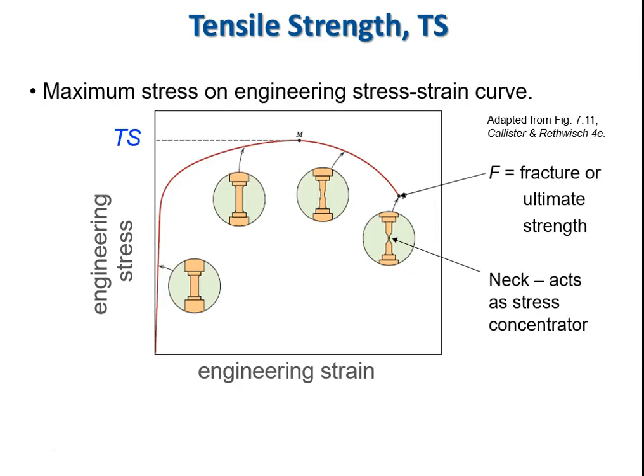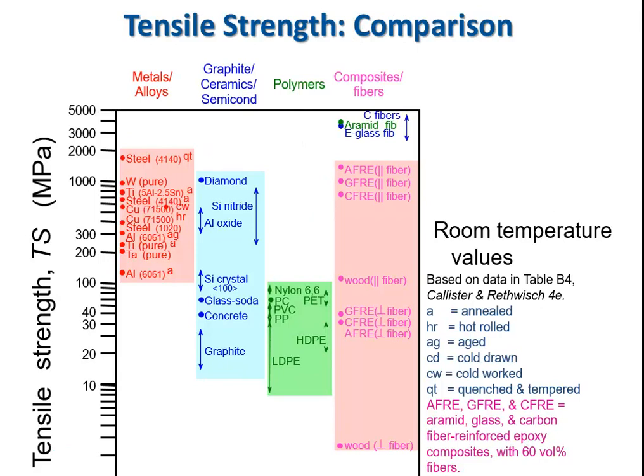It's a means of material strengthening that basically involves creating more dislocations in a material and tangling them all up so that they cannot move easily. And if a dislocation cannot move, a material cannot deform, and the yield strength goes up. So that's what's happening continuously in our test sample as we continue to strain it more and more, force it to elongate. And so we have about the same range of tensile strengths in our metals and alloys as we had yield strengths. Now that we're measuring ultimate tensile strength, we can get some numbers for our brittle materials.